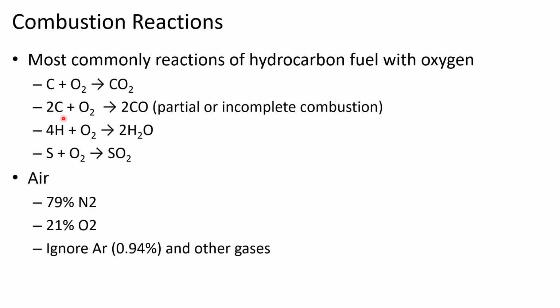However, we can have a carbon atom react with oxygen to produce CO according to the second reaction that you see here. When we have CO formation, we refer to the combustion process as being partial or incomplete. In all cases, we're going to assume that when we have hydrogen in a hydrocarbon in a combustion reaction reacting with oxygen, it forms water according to this reaction right here. And sometimes we'll have sulfur. Sulfur is a common contaminant in fuels. And when sulfur reacts with oxygen, it will form SO2 according to the very last reaction that you see there.